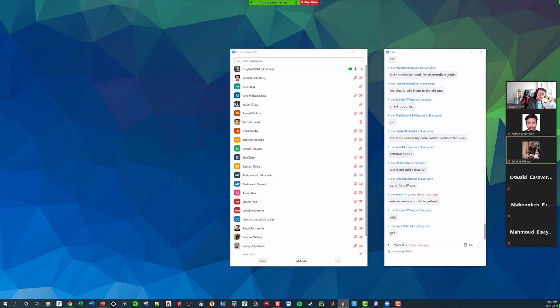But we already have 4 there from our previous stiffness matrix. If we look here, entry 2, 2 appears up here, and I'm just going to try and highlight it, and it appears in here. So when we're dealing with our global stiffness matrix, this entry right here is going to be 4 plus 4, which is actually equal to 8, right? Does that make sense to you guys? Yeah, all right, I'm getting the yeses.